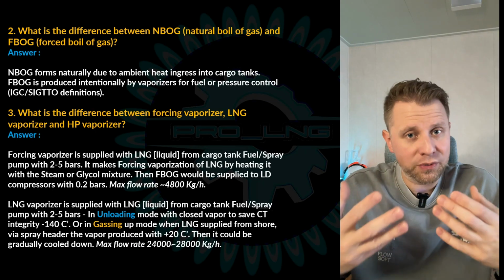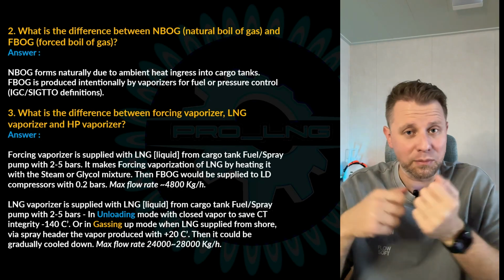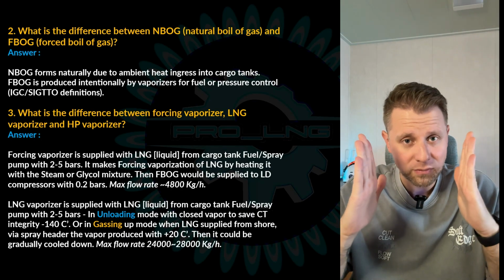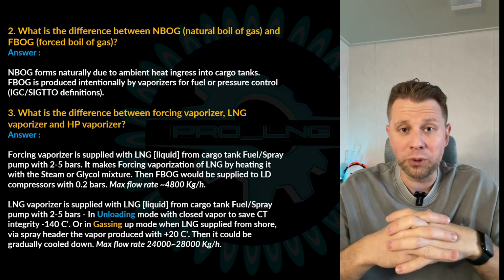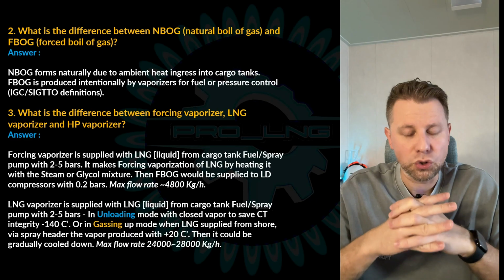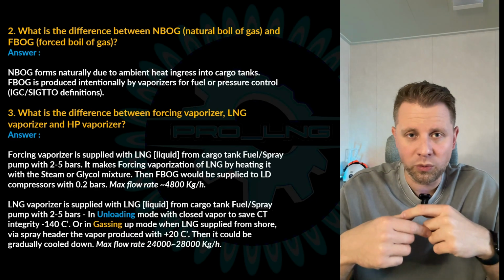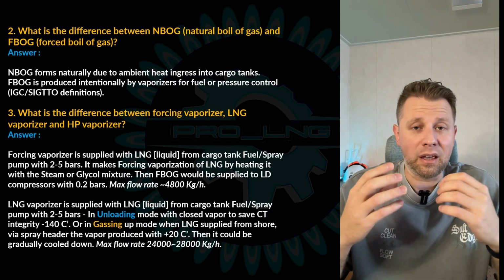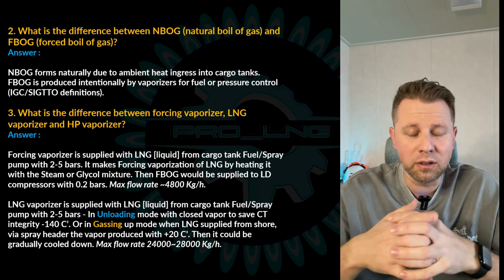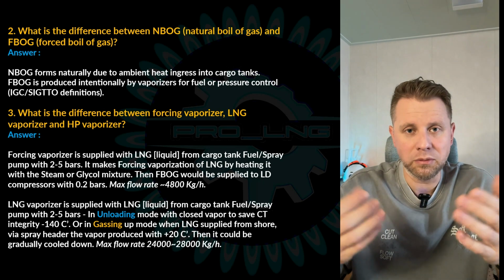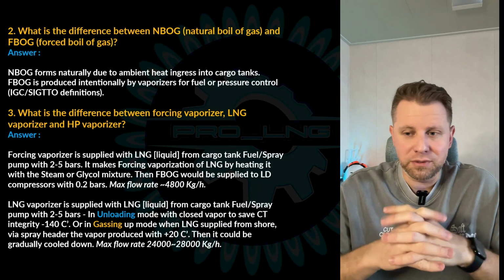If you don't produce forced boil-off, you will start sucking more and more, and the tanks will become vacuum. Eventually, due to low pressure, you will have an ESD. So that's why you need to take the liquid and warm it up with steam or glycol, and then you will have pure gas at the entrance to your engines, at plus 20 degrees Celsius. So that's the main point.